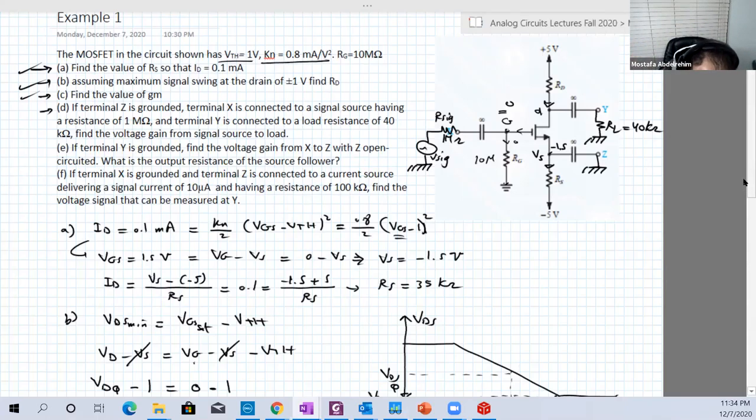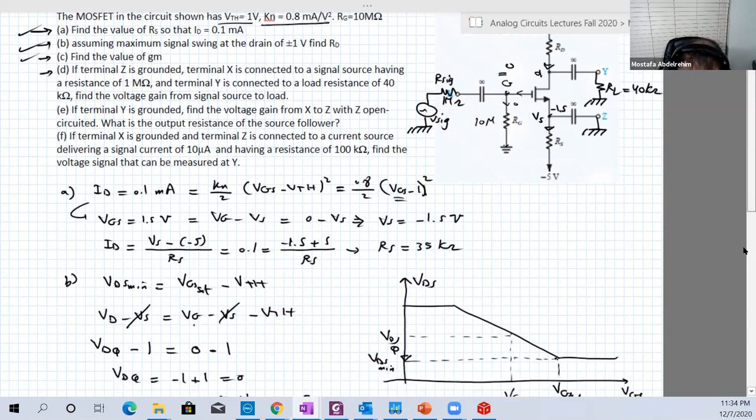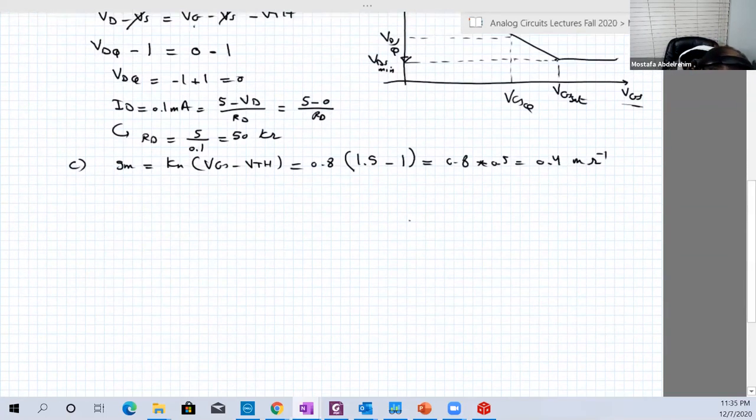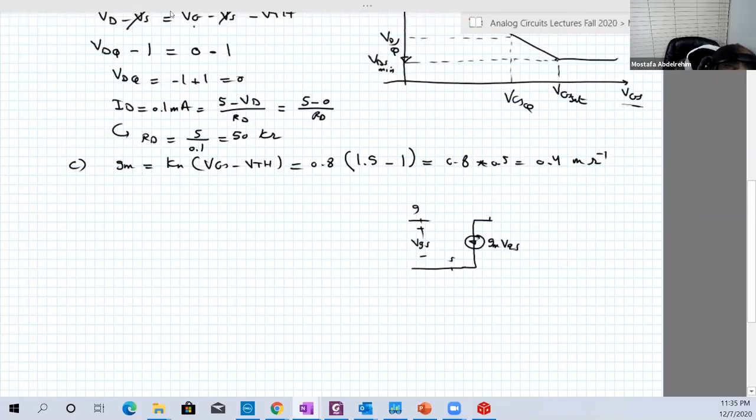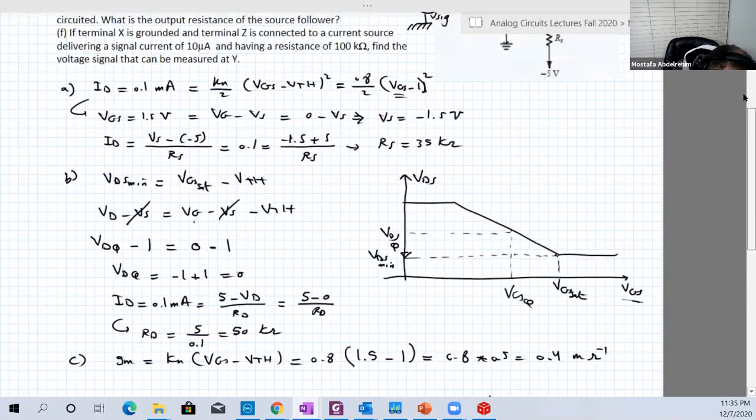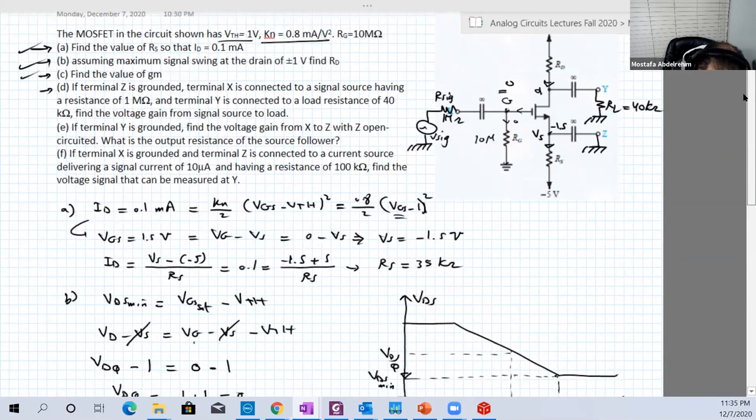Okay, good. So let's draw the equivalent circuit. I'm going to start with the transistor's GM VGS. Here is the gate, here is the source, here is VGS, here is the drain. And let's connect the other part of the circuit. So between the gate and the ground, there is RG and R signal, V signal.